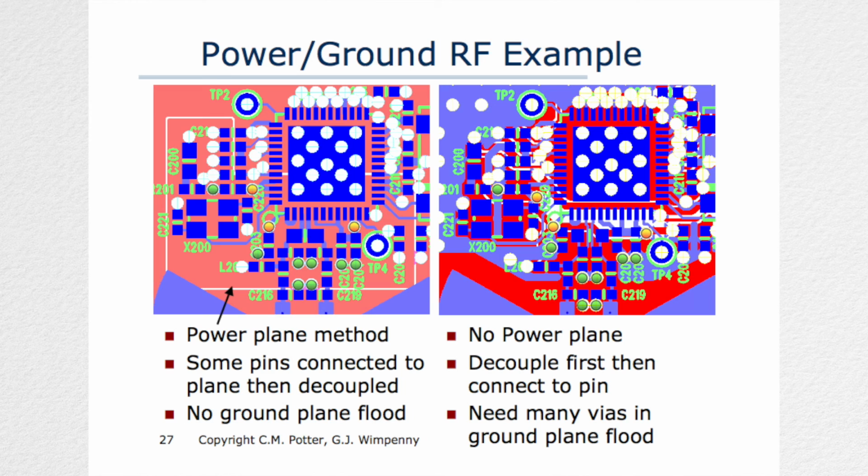And anything that comes out from the chip, which it does in the case of the transmit mode, can get down onto the power plane and then radiate to other pieces of circuitry without being adequately decoupled by the capacitors. So it turns out that you can get a much better performance simply by tracking things in a different order. So on the right-hand side is what's happened after I had a word and changed the way in which it was done.